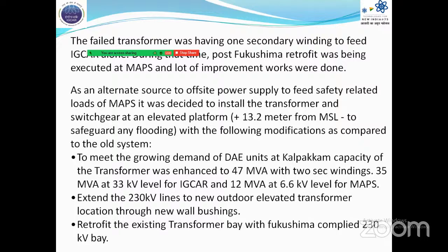The existing transformer was located at plus 11.6 meter from MSL, so a 1.6 meter cushion is obtained. This higher elevated platform is to be built, and the switchgear and transformers installed over it to safeguard against any flooding condition.